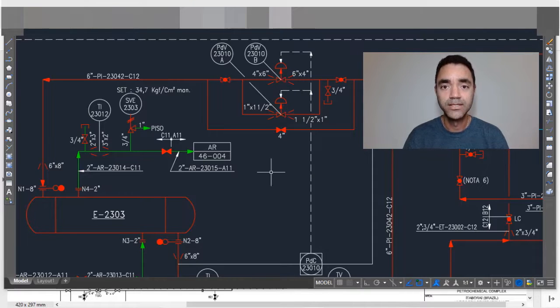and the output of the PLC goes to two control valves. See that this control loop is different from the previous arrangement, because now we have a split range control. So part of the signal will actuate the small control valve, and the remaining signal to the process will actuate the biggest control valve. Or it can be the opposite, depending on the control philosophy of the plant. So it's important that you get familiar with that. It can be in the operating manual or eventually in the interlock description of the plant.